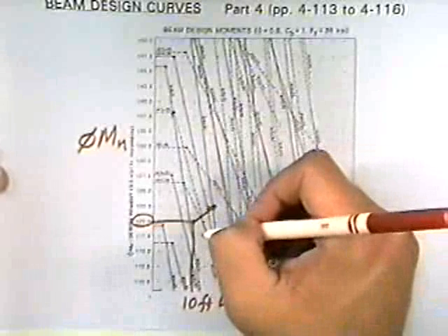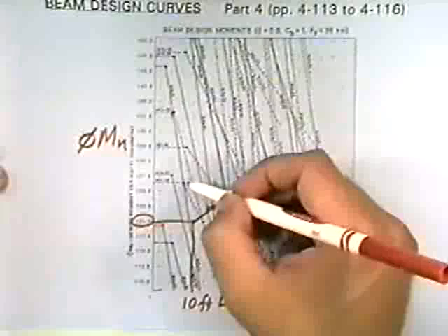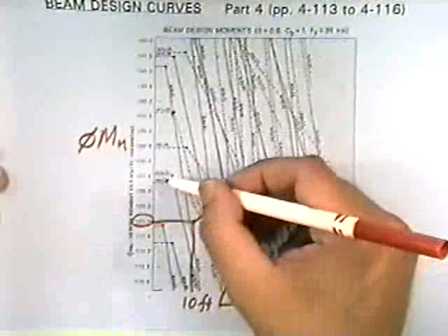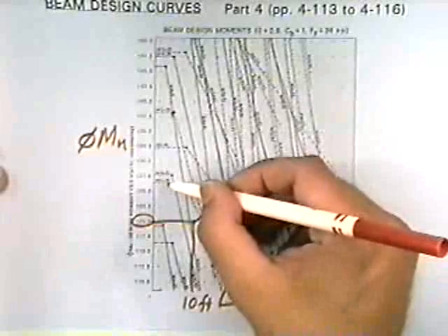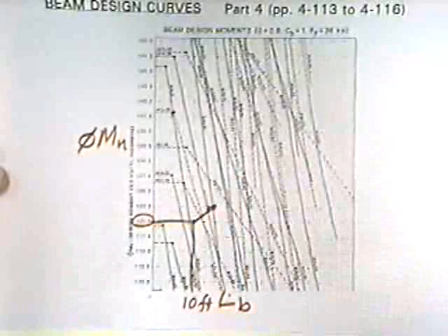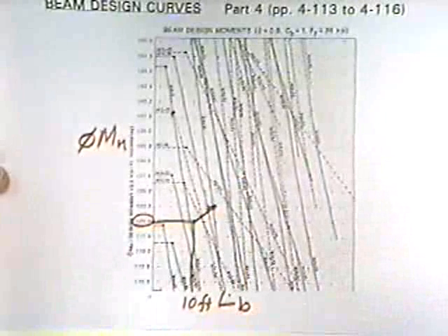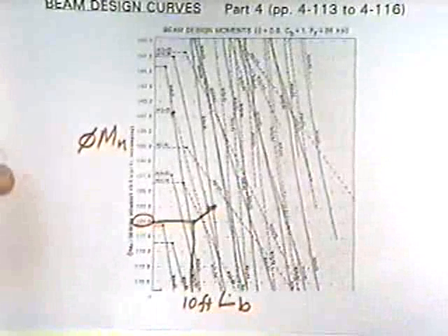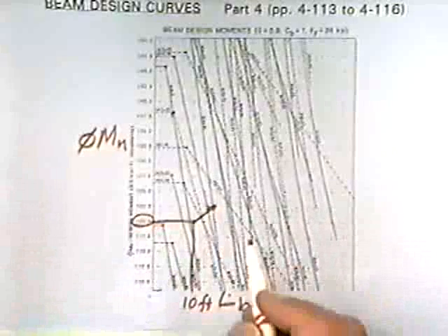Okay, and note that that's less than the W12 by 35 in weight, as well as the W10 by 39. The second set of numbers after the X in the designation of the section is the weight per foot length of beam. So you got the 10 feet from the distance between the braces?